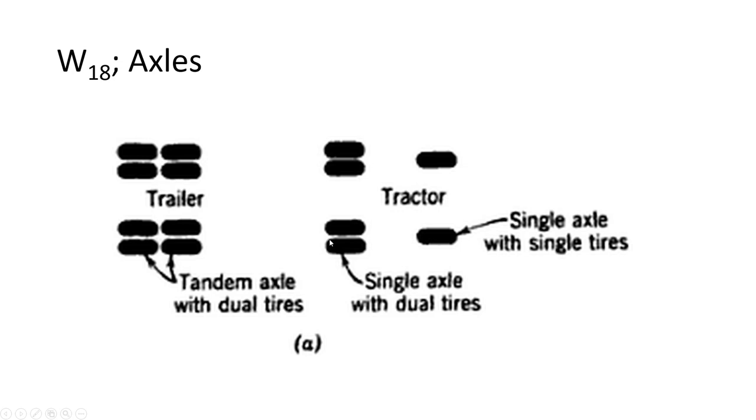So this is if you picked up a tractor with a short trailer, I guess, on this one, and dipped its tires in ink and then set it on a piece of paper. This is the diagram that would come out, right? This is where the tires are touching. That's where all of the load, whatever that truck weighs, all of its load has to end up, in all of these dark areas where those tires are touching the pavement.